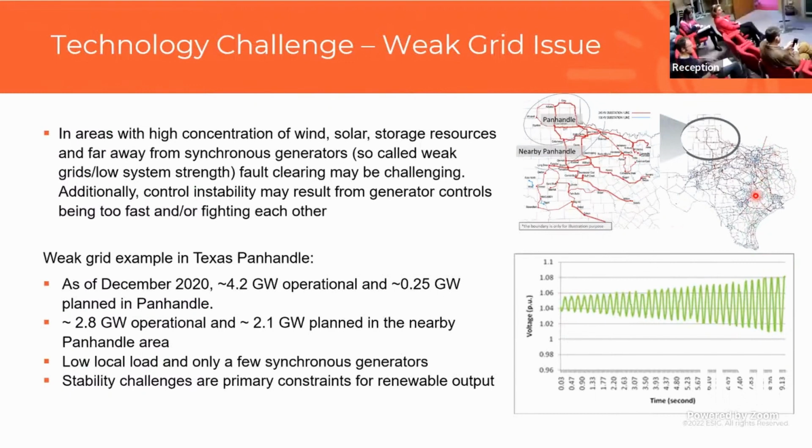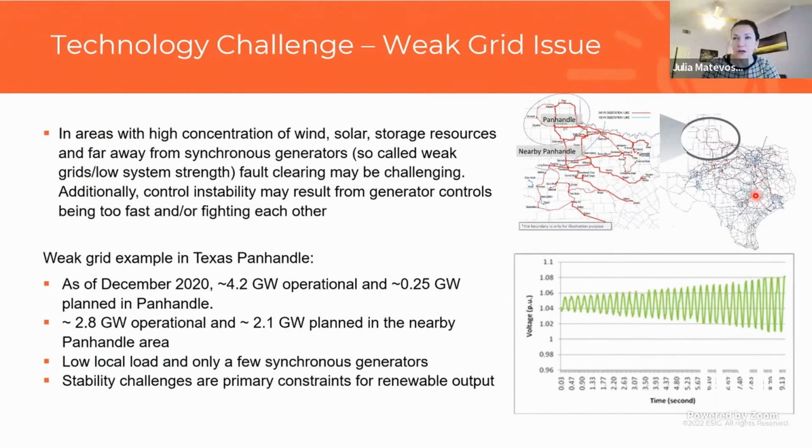Sorry, Frank, I can see you want to ask a question. Frank? Yes, so I had a question. Earlier on, you mentioned that the response of the inverter-based loads was fast but not instantaneous. Do you know approximately what the delay in the response is? Is it 50 seconds or? So for frequency response, it's about 250 milliseconds. Okay. For current injection, there are different requirements. If I remember correctly, in GB, the requirement is within 20 milliseconds. Okay, great. Thank you. Sure.